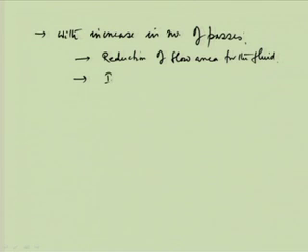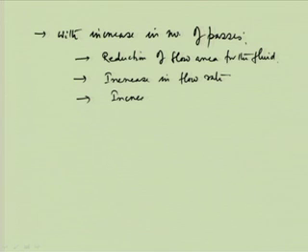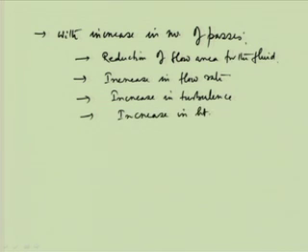This will increase the flow velocity, which means an increase in turbulence, and this will increase the heat transfer coefficient. But at the same time, there will be an increase in pressure drop also.